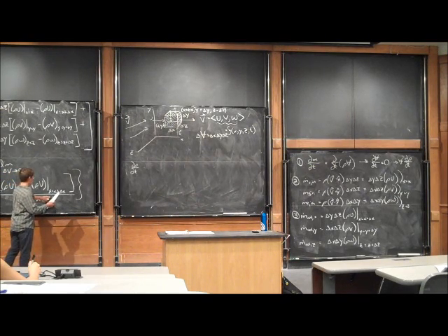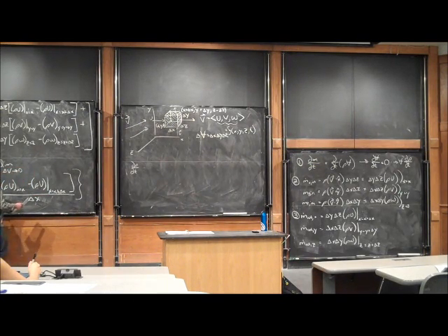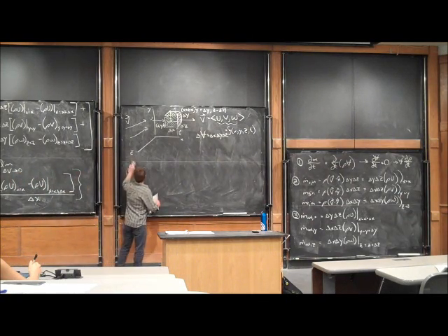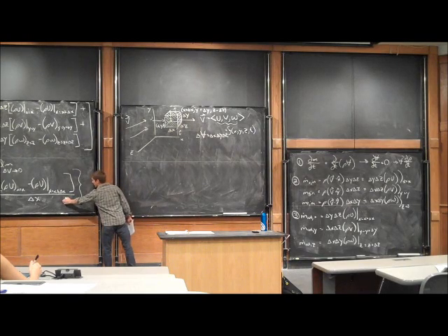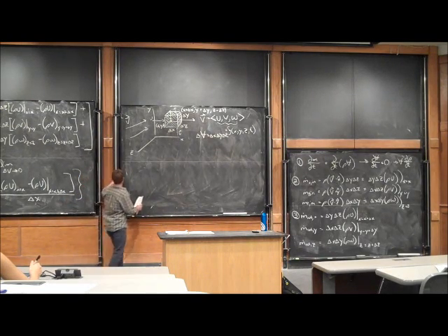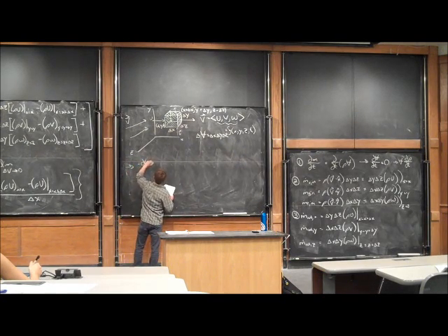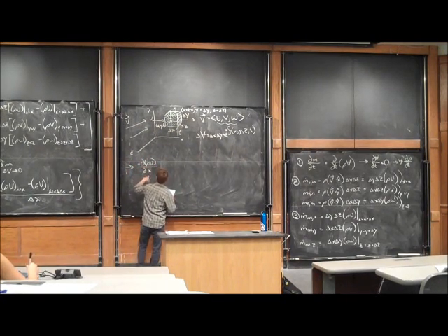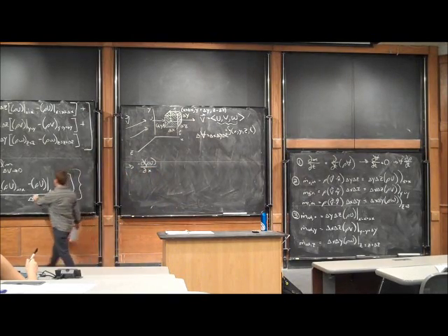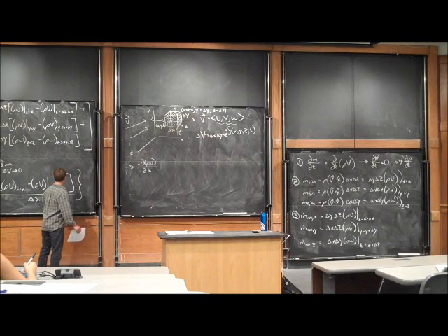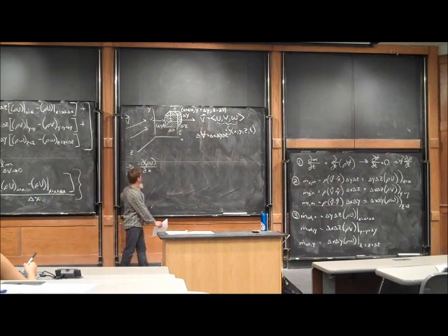So this is actually a negative of the derivative. So this entire term, I'll just write that. This limit and this dividing by delta v ends up just getting us negative del rho u del x. If this had been plus delta x, and then that had just been x, that would be a positive derivative. That's not how it is. It's x, and that's plus delta x. That's where we got the negative sign in front of our derivative.